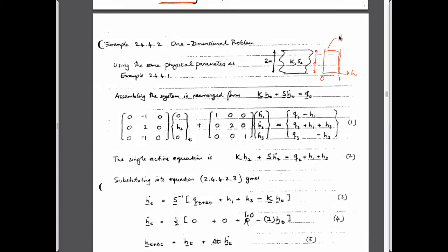So this is t equals 0 plus. In other words, we change this boundary condition on the top node. This is t equals 0 minus. So before we change anything, it's just this one uniform head throughout the system of magnitude 1. And then all of a sudden we change it at this particular node and it will respond. Over time, in theory, it will look progressively like this. And at time infinity, if we hold this value constant, it will be like this, t infinity.